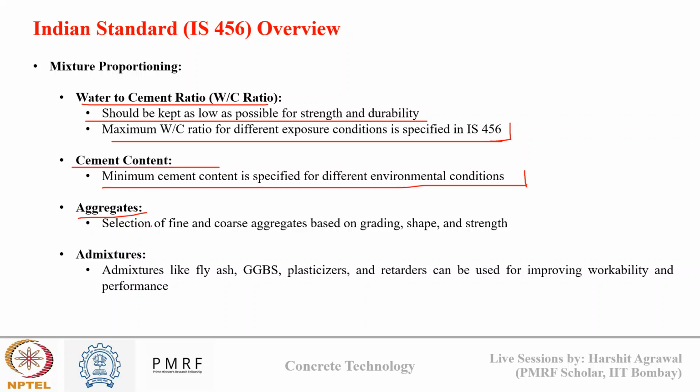Aggregates. So selection of aggregates, fine and coarse aggregate, is based on grading, shape, and strength. So this thing also you will see when we discuss in detail about mixture design today. And admixtures. So admixtures like fly ash, GGBFS, plasticizers, and retardants can be used for improving workability and performance. That is what the IS 456 code is saying.